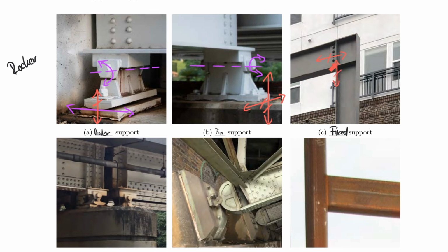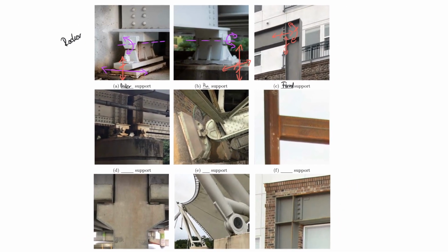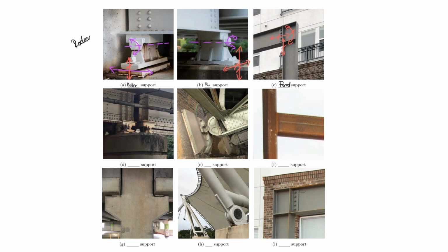So the column here is really the support in this case. So we have the beam that is rigidly connected to the column, and therefore we actually end up with a system that cannot rotate and cannot turn about a pin axis. So those are the three different systems, and now I prepared some more pictures for you just so that you get a better variety of it. And let's take a look at them and appreciate the differences.